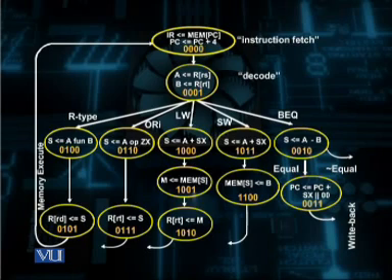As you can see in this diagram, the contents of the register RS are transferred into the temporary register A, and the contents of the register file location RT are transferred into the temporary register B. The next step very much depends upon the result of the instruction decode.